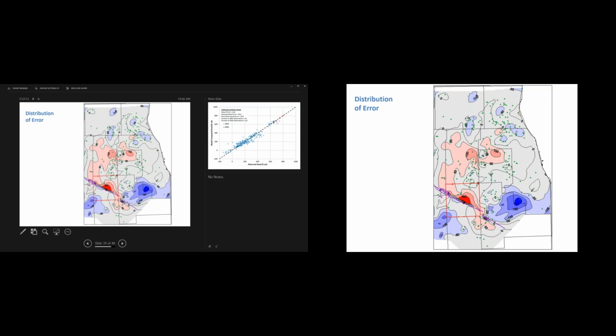Yeah. Most of these are production wells, and we've gone out and measured a static water level when the well's been turned off, 15 minutes, an hour, 4 hours. These are not exceptional calibration targets like we're dealing with in the Mahomet, where we do have dedicated observation wells.